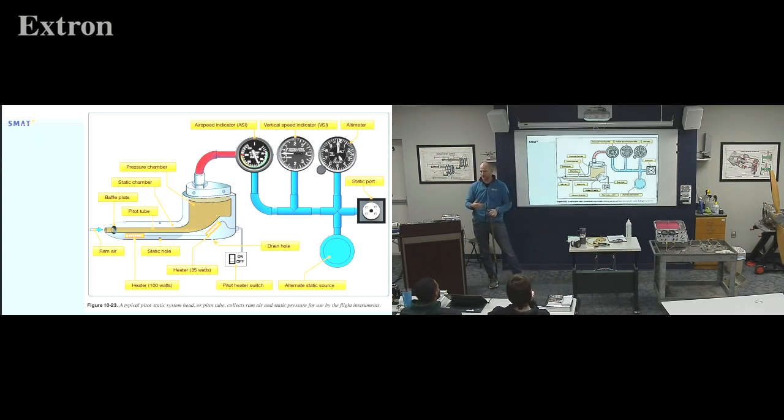That's pretty self-explanatory, right? Our altimeter has an aneroid, we called it. It's going to be a diaphragm or baffles with a vacuum in it, probably baffles. So all the altimeter needs to know is what's the pressure outside the aircraft, and I'll compare it to an absolute vacuum, and I'll tell you how high you are if you tell me the adjustment I need for today's pressure. Our vertical speed indicator, we talked about already how that is similar to an altimeter, but there's a bleed hole in it, a calibrated orifice. And as we go up or down, as the pressure changes, it'll tell you how fast it's changing. So it's connected to our static system.